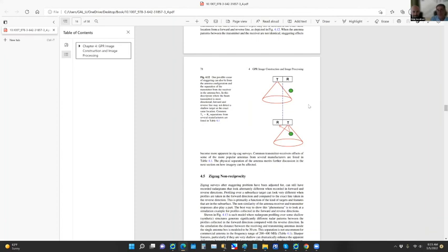That's crazy. But you know what some people would do? I think it was the people at the University of Vienna, the archaeological group under Neubauer, they would often go to a site and do a zigzag survey, but they wouldn't rotate the antenna. So they would keep the antenna and then come over and come backwards. Yeah. So I would say there is no exact answer to your question, but doing a zigzag survey, you can record both features on a structure at the same time, giving up a little bit of homogeneity to your image.